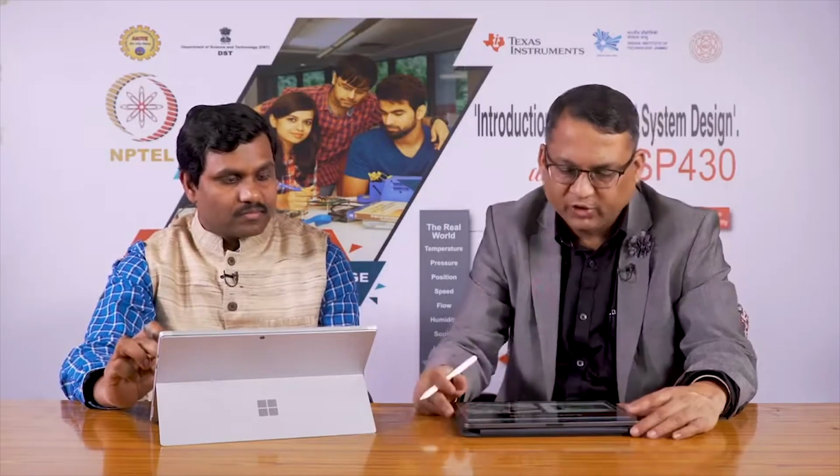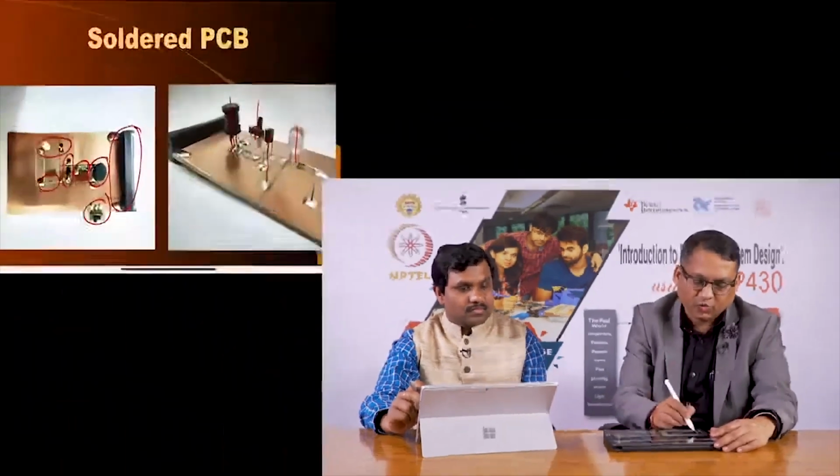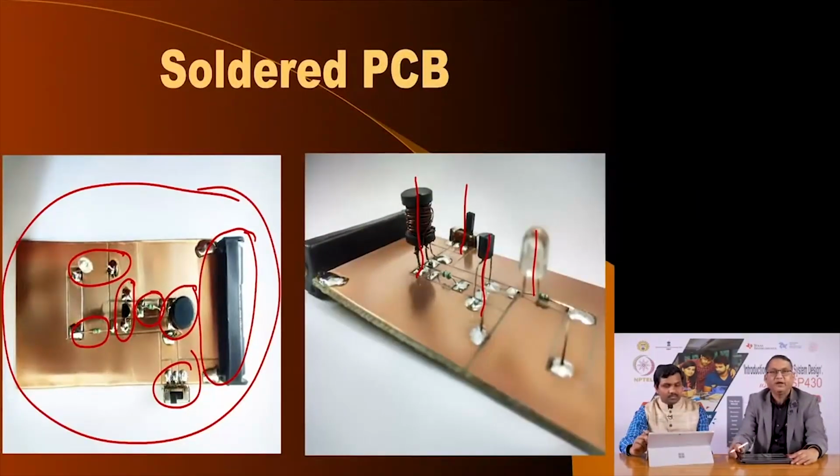And in this, what you need apart from soldering wire and soldering iron is a cutter for cutting the components to appropriate size, and of course, you need what is called a watchmaker's file, which is a very thin file for removing unwanted copper to create these islands. Apart from that, you need a hacksaw to cut a PCB of appropriate dimension. Other than that, no specialized tools are required for prototyping a circuit using this Manhattan style PCB.